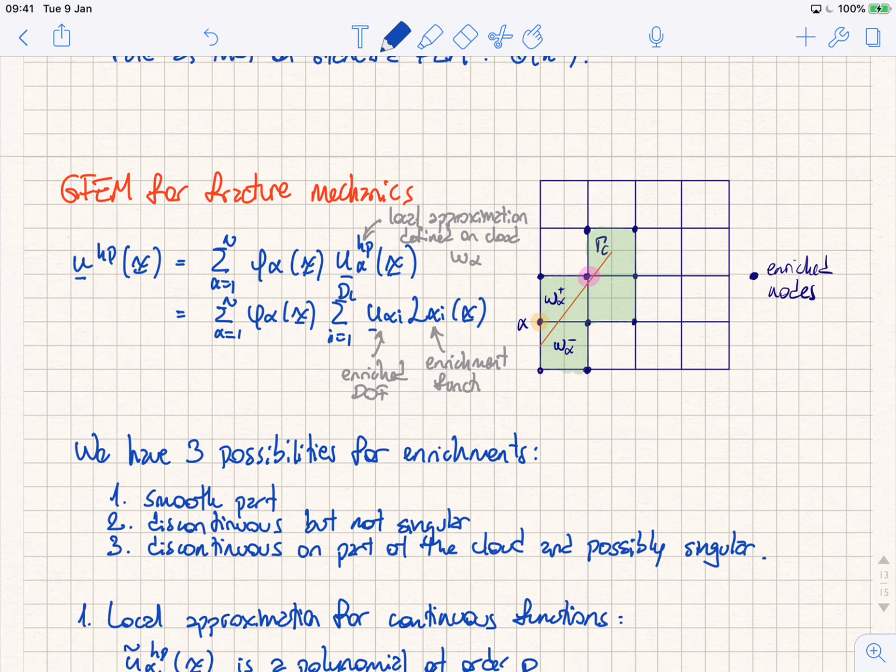The crack tip may correspond to an element. Yeah, but let's take a look at that element that always is going to contain the crack tip. What is happening if I make it smaller and smaller, and I keep enriching only the nodes of that element? What is your intuition?